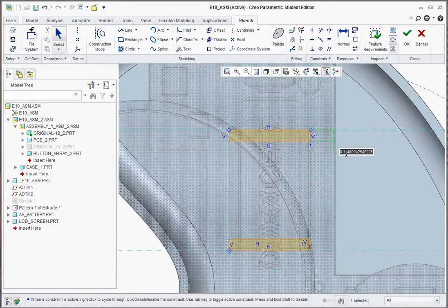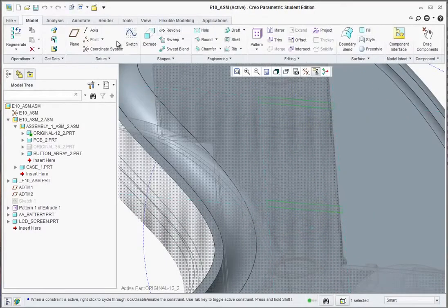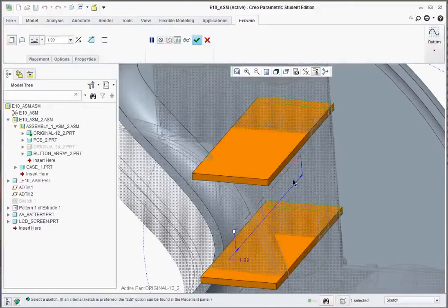The typical wall thickness, actually, with plastic parts, it's usually less than 75% of wall thickness. So we can make them actually 0.07. Otherwise, you get some shrink that occurs in those areas and it might be undesirable. So we'll go ahead and hit OK, and we'll go to extrude.